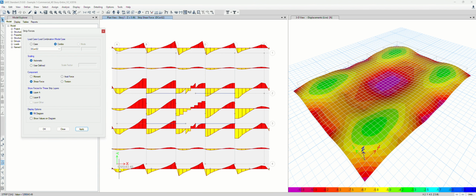Some design forces, you could see that along the design strip near the column has a relatively big moment and shear forces. Absolutely, near our wall you see much bigger shear forces. Obviously we saw the biggest shear stress, which is shear stress multiplied by the design strip width and depth. You can calculate the shear force.